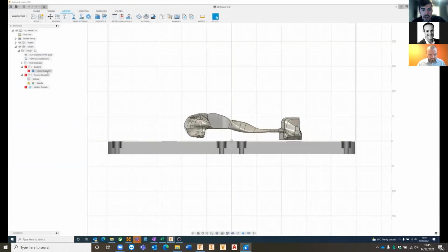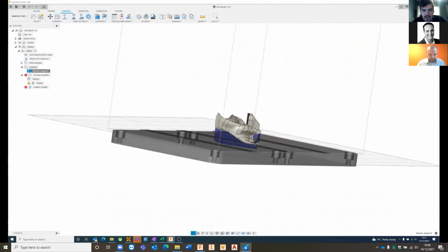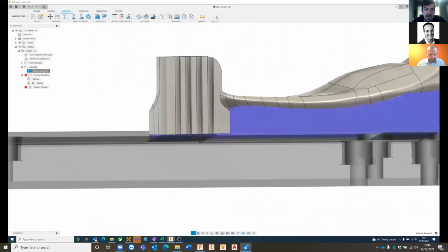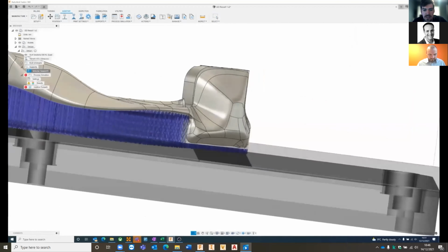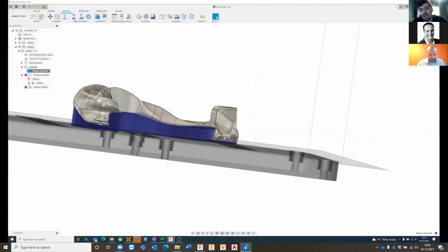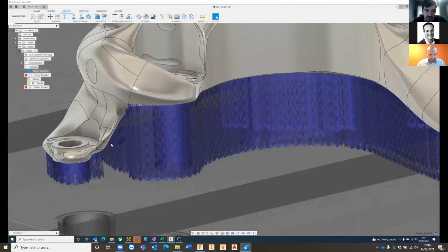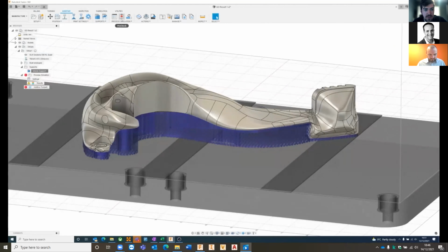the print of our particular objects, and this will allow us to then have a look at different areas that may require adjustments. So as you're printing, obviously you've got certain areas that may need a bit more support or may have a bit of deformation. And this additive simulation will essentially run through a simulation process to ensure that those areas are highlighted and considered, and we can then export a compensated model that will ensure that those areas are then printed to the design intent, essentially. So in this case, we've just added those supports here.